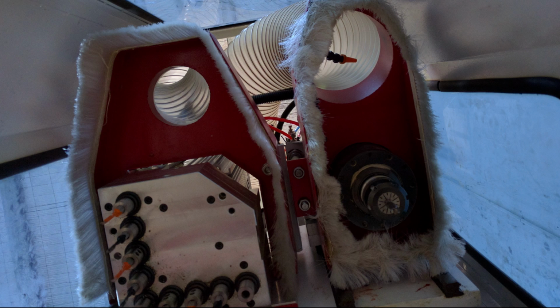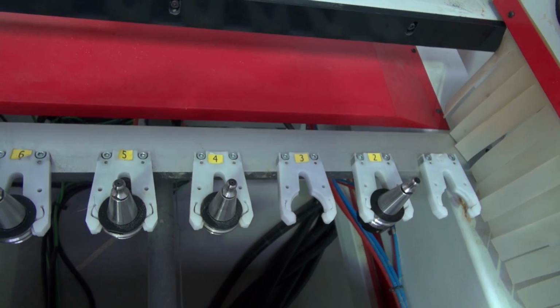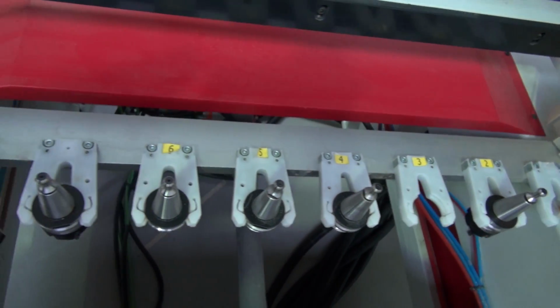The machine tooling is a very sensitive and important aspect of the machine setup and functionality. Machine tooling consists of a number of various tools. These tools are drills, cutters, skimmers, etc. Tooling on this CNC router is located in 2 different locations. First, the prime location is the cutting head, which holds the cutter and all of the drill bits. Second is the tool rack, which holds the skimmer and optional locations for other relevant tooling.